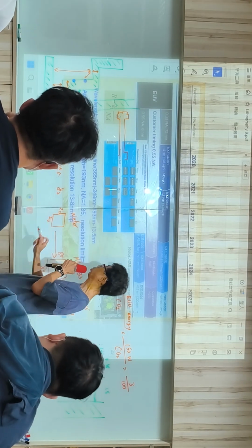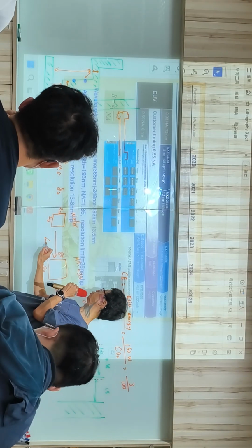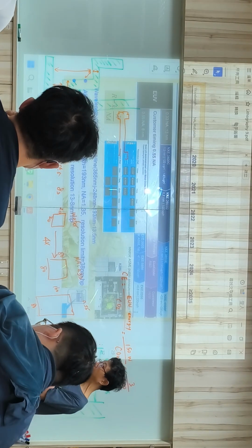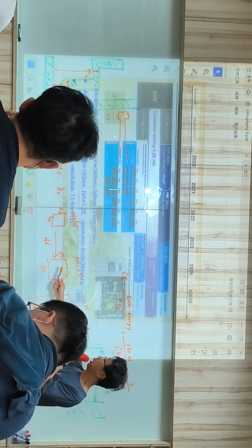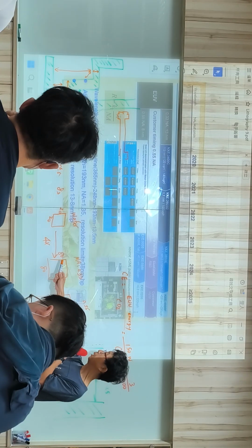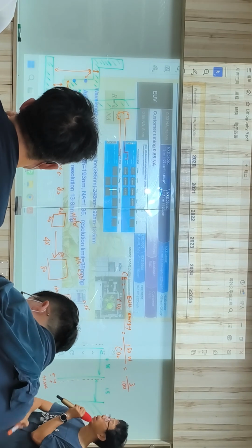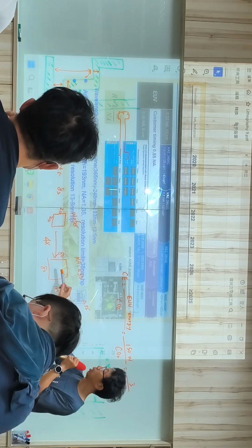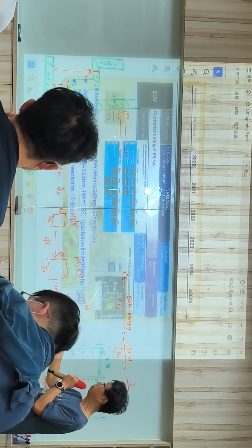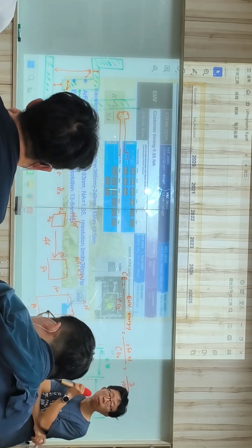We want to print 20 by 20, and because for 0.33 NA the ratio is 1 to 4, on the EUV mask the contact should be times 4, so 80 by 80, right? But for high NA, now in the y direction it is 1 to 8. So the contact becomes 160 in the y direction. In the x direction, it becomes 80.